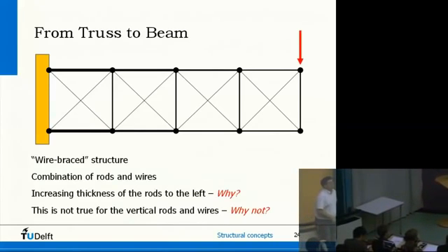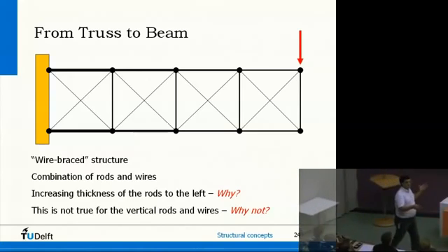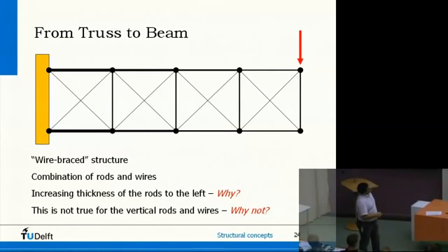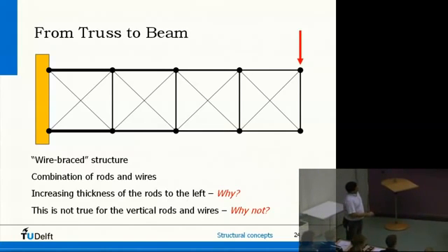We can extend that. This is a beam with 4 cells. And actually what we do is to synchronize 4 of these cells and we have a truss structure of 4 cells. If I apply a load here, the load has to be taken up by the structure and transferred to these points on the left side. So the load has to travel from right to left. What you see here is that we do it in this case with some wires. You also can do it of course with these bars. There are bars in here at the top and the lower side and also here in between.